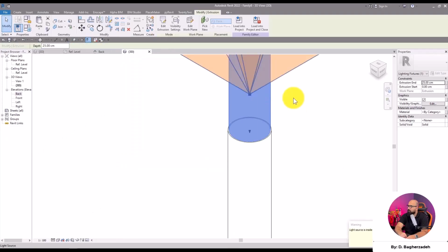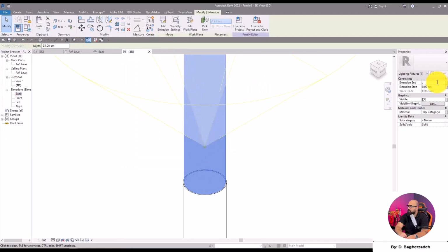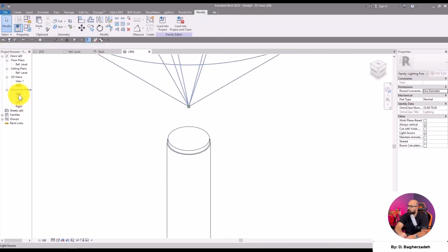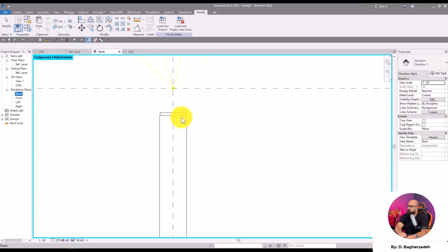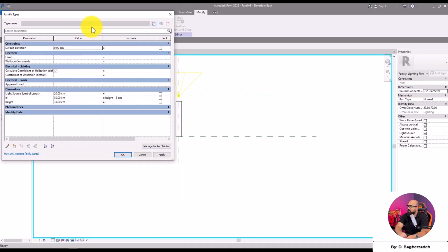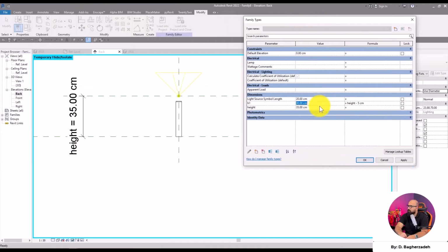And then after that, we need to specify the extrusion end. So 0.5. And now this extrusion works based on the cylinder below it. They would move together completely. As an example, let's go ahead and change the height to 20. See? They would move together. How about 15? Same story.